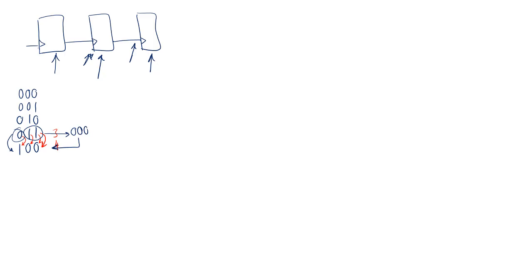And if you have connected this counter output to something, for a moment your output, which is going to be connected to the input of some other block, is going to be 000. And this could cause a problem. Remember, for example, for building an ADC, if you remember the dual slope ADCs, we used the counter and counted things, and sometimes when we reached a certain number, we wanted to stop the counting.